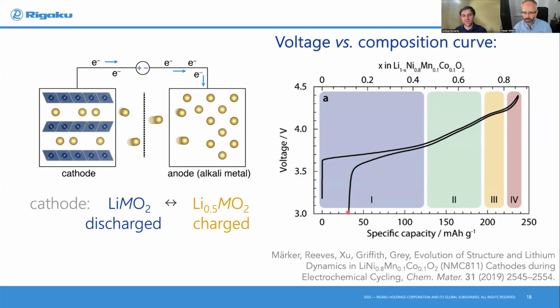And then often what you'll see is that as you go to discharge the battery, you don't get the exact same capacity out. There's some lost capacity. That's an inefficiency in the first cycle. You can't get all of the lithium back in. But the voltage, as we go through these cycles, is going to increase as we're charging the battery and decrease as we're discharging. And it oftentimes isn't perfectly smooth. There's some shape to it. You can imagine that the exact shape of the cycling curve is going to depend on the chemistry involved, the energetics of the various phases involved. And optimizing this cycling performance is a big challenge.